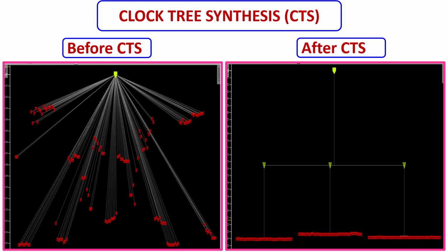Clock tree synthesis is the process of distributing the clock signal, inserting clock buffers and inverters, building a balanced clock network, and minimizing the clock skew. Delivering clock to all sequential elements with controlled delay is CTS. What problem does CTS solve? This solves clock skew and clock latency.